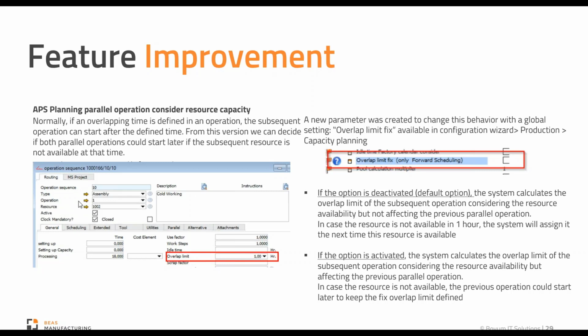Normally, obviously, if you're in a chemical industry, that doesn't make any sense. You mix something, you have to wait for the whole mix to be ready before you can go to the next step. But when you're talking about discrete manufacturing, and if you're making small parts of something, you can do the first, the second, the third, and those that have undergone the first operation can actually go to the next operation already. You don't have to wait for the whole batch to be ready, okay?